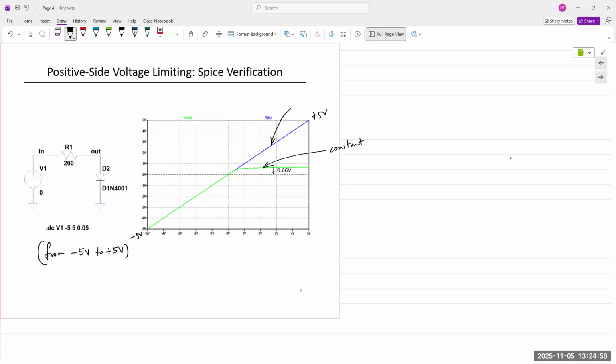A diode curve, if you remember, curves up, but there is a slight slope to it. The slope is exaggerated here, but is present in a real diode. So when you run an LTSpice simulation, you might see a little upward curve on that V out characteristic. This is something you can easily simulate, and I would highly recommend you do. The circuit is given to you, and the answer is also provided.